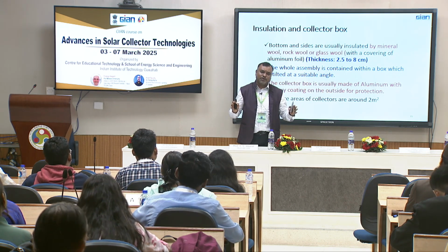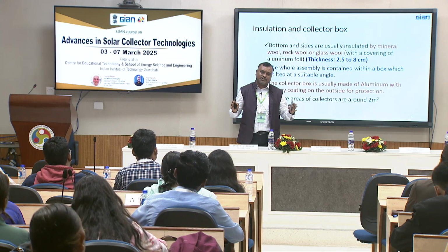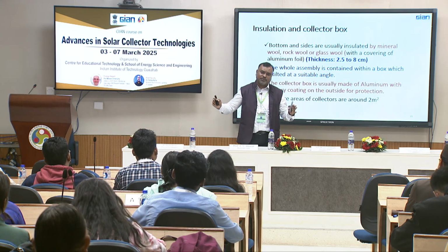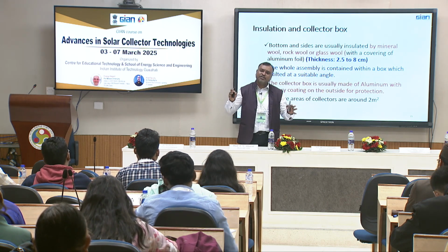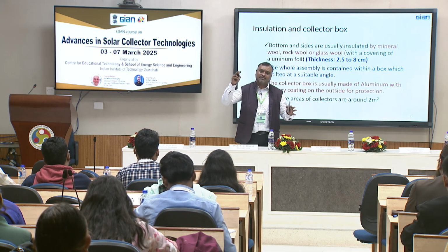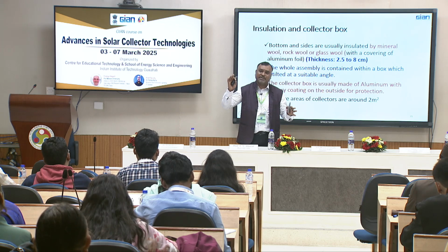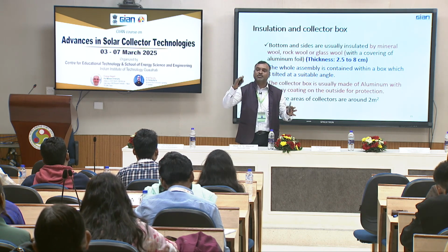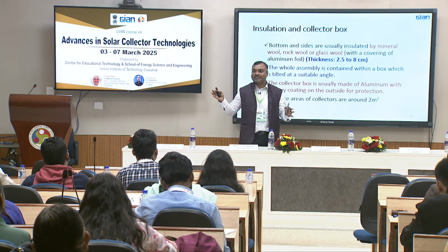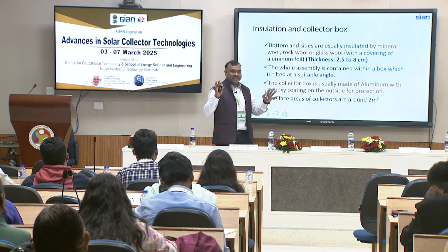So you start with November or December and end with maybe March. During that time you are going to operate it, and during that time you optimize beta, the optimum beta for maximum energy, okay. Otherwise if you design beta for June, July, August, that might not work for a place like Paris during the winter, okay. That's just the logic.